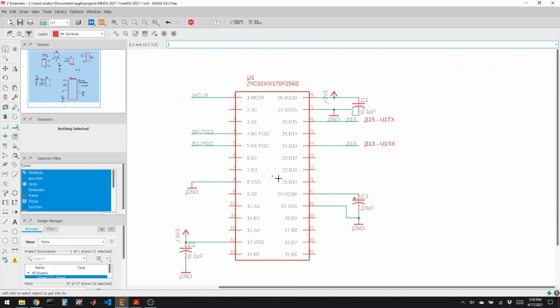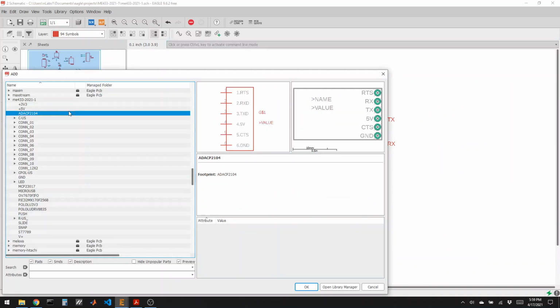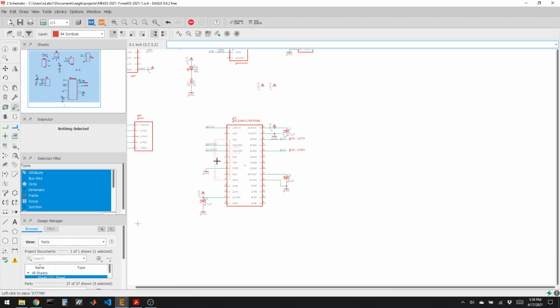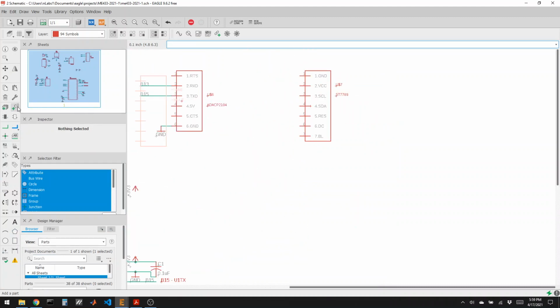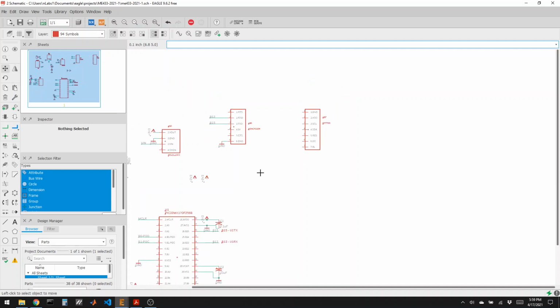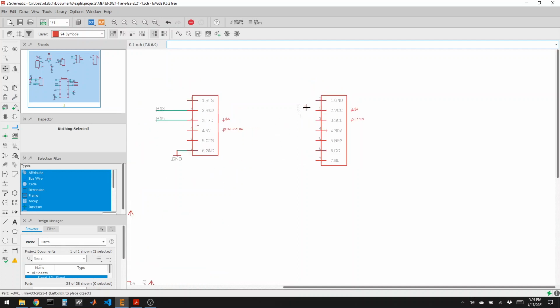Okay, what else do we have? We're going to be talking to an LCD screen, the ST7789. And it needs to be powered by 3.3 volts on the VCC pin. And it gets a ground connection, ground pin, and then the clock, data, res, and DC pins will all be connected. So this display uses SPI communication plus 2 more wires. So it's not quite standard SPI.